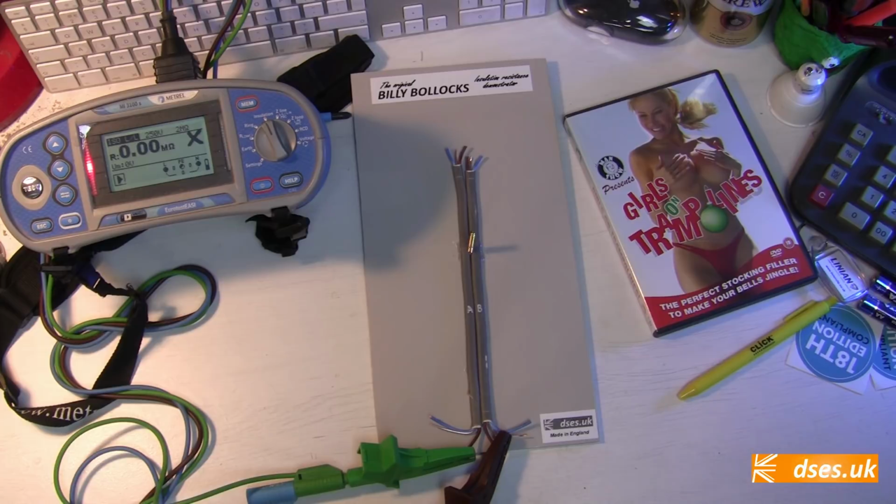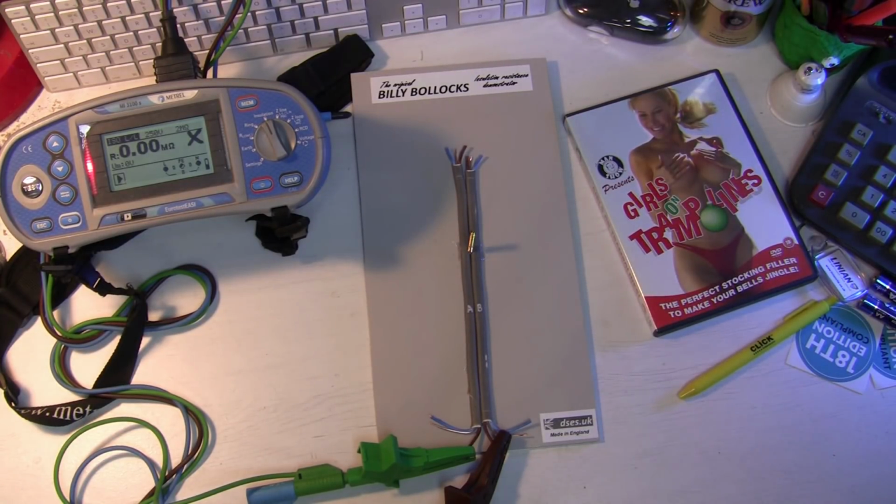Now, although my insulation resistance read as 0, out in the world it could be anything, and if it's anything less than a megaohm for a 230 volt circuit, then it doesn't comply with BS 7671, and funny things may start happening. The only way to have this kind of fault fixed is to hire a proper electrician with the right kind of kit and enough noughts to track down the fault and put it right.